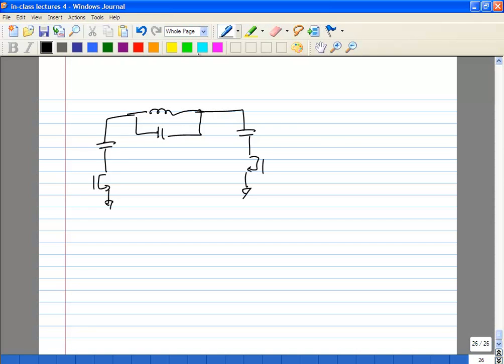Now if you look at your discrete tuning, this is a continuous tuning. So far we have seen single-ended implementations. You can also do something like this for the discrete tuning. So if this is C, you make it something like this. And of course, if your transistor layout is such that the source and drain are not symmetric, then you may need to do something like this: you need to have half the transistors switch the other way. Sometimes that can happen from layout, depending on the number of fingers and so on.